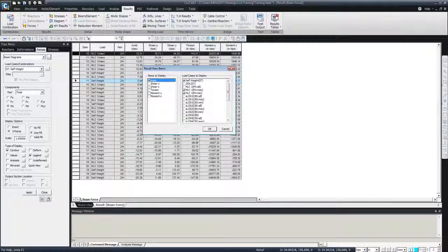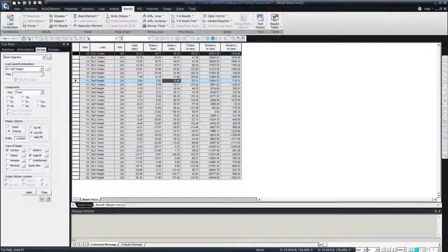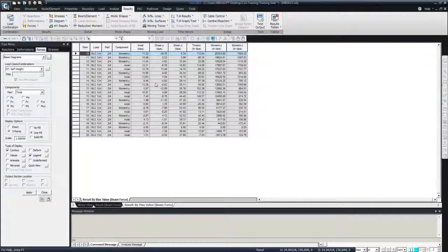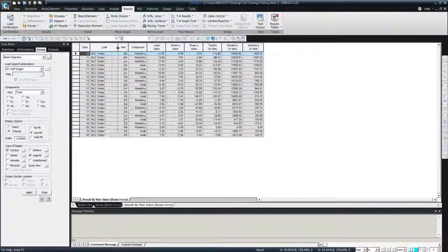Let's say I want just the axial force and then the bending moments, and under just moving load case maximum. And say OK. It's going to give you this option. For example, for element 10, I know that when the bending moment component is at its maximum, it's going to give me the different options for the axial, shear, and the torsion. So it's going to sort it based on this. All right, so here you can see the concurrent forces based on these.